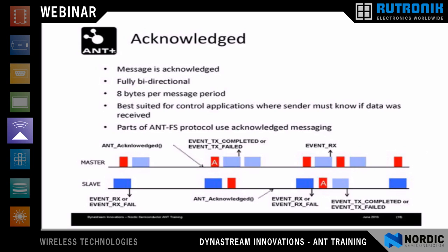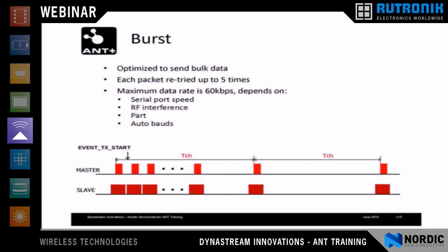And you can see that if you start an acknowledgement on the slave side, then your transmitter will have to open up a transmit again to send back the acknowledge. So there's a little bit more airtime required, and therefore slightly more power consumption. But again, we're not talking a large amount, we're talking just microamps.